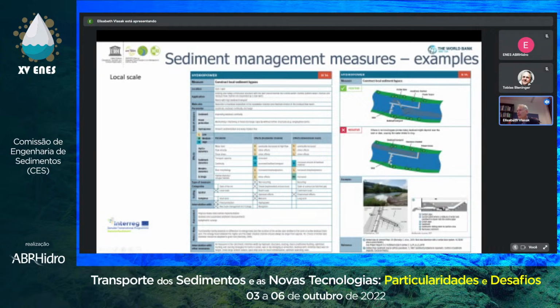Even at the runoff schemes, you can go for bypass systems. Like here is a tube, a pipe you can put in, where here is the powerhouse and here is the head race. You have so-called vortex tubes with a spiral flow. The sediments that go towards the powerhouse, and it's also fine material, are diverted back to the river. So we can have this kind of pipe to go back to the river. All that is also described in text in this document.